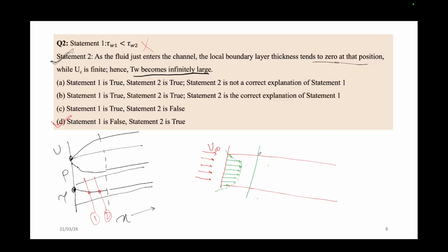Similarly as it is near to the wall, its velocity is less, and because of this friction, as in physics, the friction in one layer has certain effect on the next layer, right? So now it will reduce the velocity of the next layer like this way. Two layers or three layers, it will reduce the velocity. After that, it remains almost fixed.